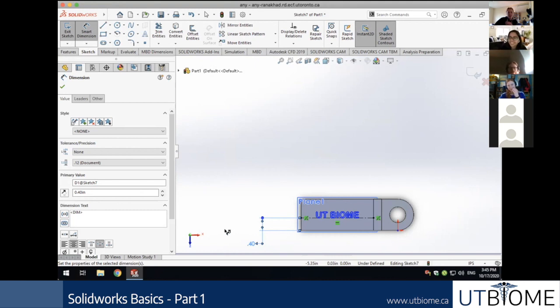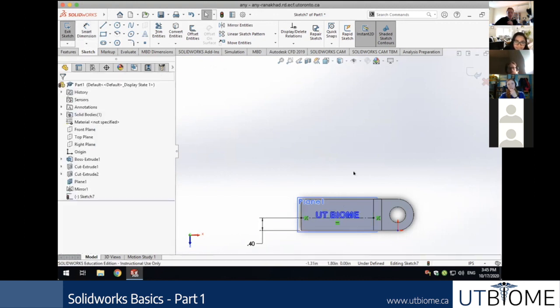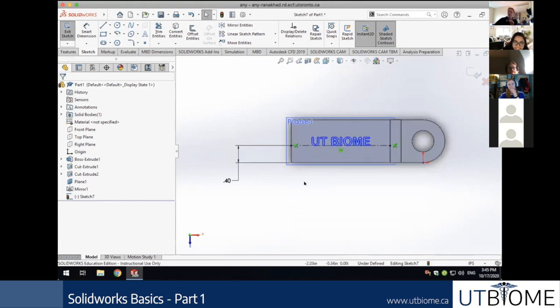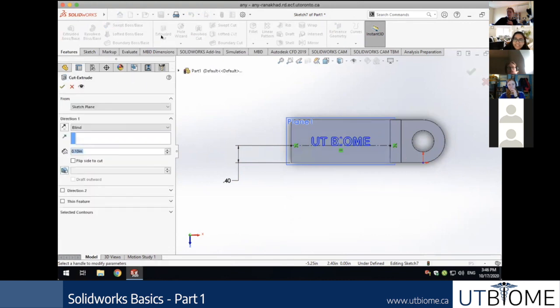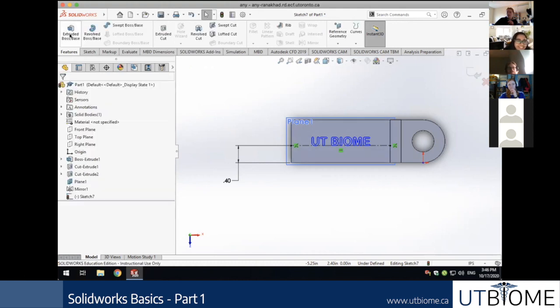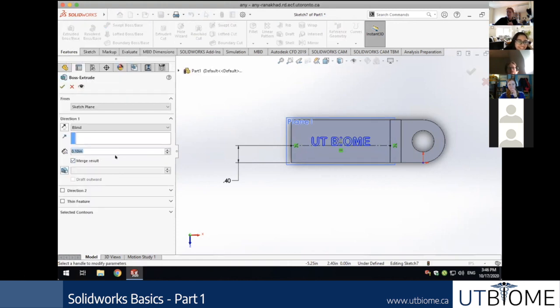So you can just hit the check mark now and do your cut or your extrude. And I'll just make sure it works while you do that. So go to features. Make it center properly. Perfect. Features. You're already in the sketch, so you don't need to click anything. So just go, do you want to cut or do you want material added? Cut. Okay, so click Extruded Cut. Oh, actually, this would be hard to clean. I want material added. Okay, fair. Okay, so hit the X on the cut extrude. And you're going to go extruded boss/base. Yeah. It'll know by default that you want your text.